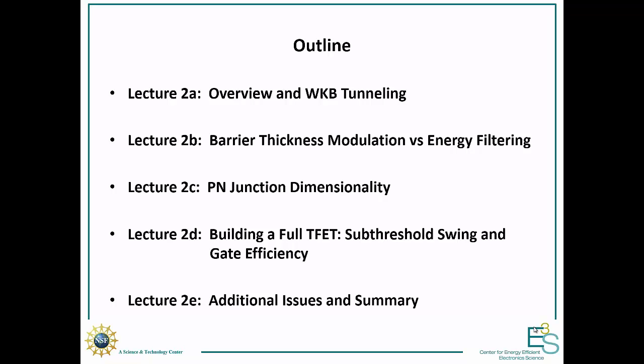In the first part, I'm going to give an overview and talk about the basic WKB derivation of tunneling. Then I'm going to talk about the two ways to get steepness in a tunneling switch. We can either control the thickness of the tunneling barrier, or we can use energy filtering, where we cut off the electrons that can tunnel.